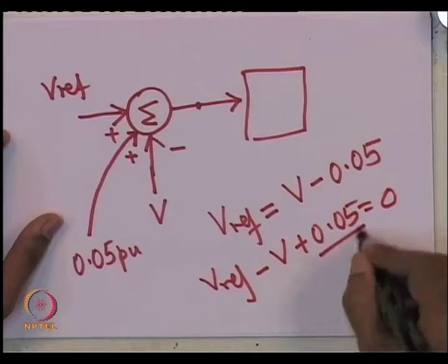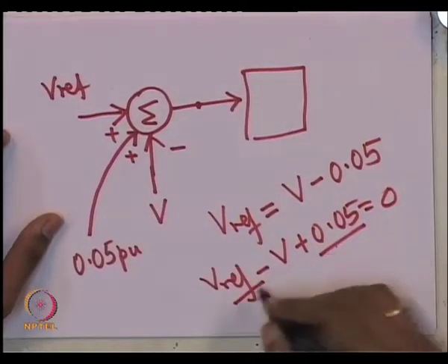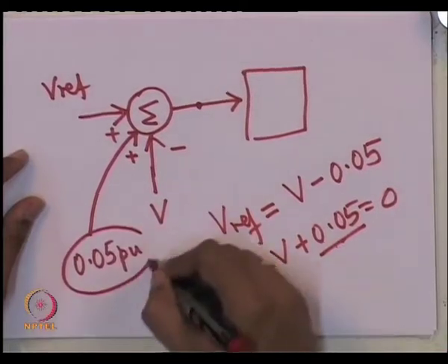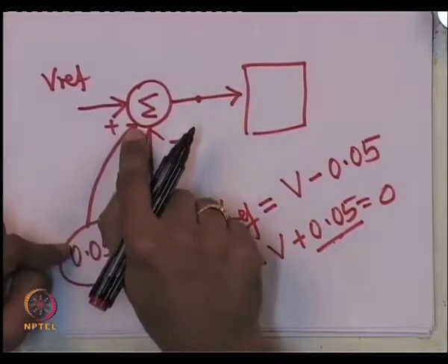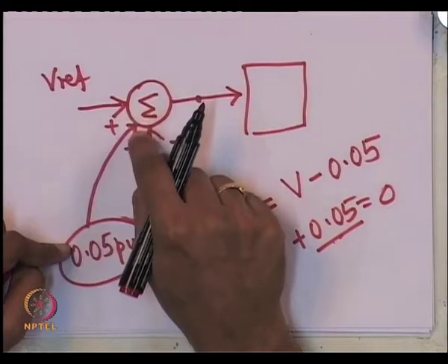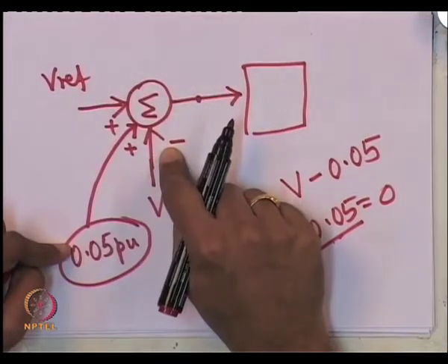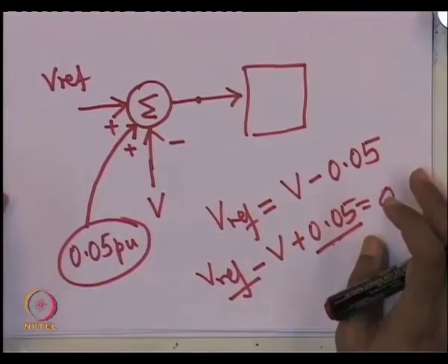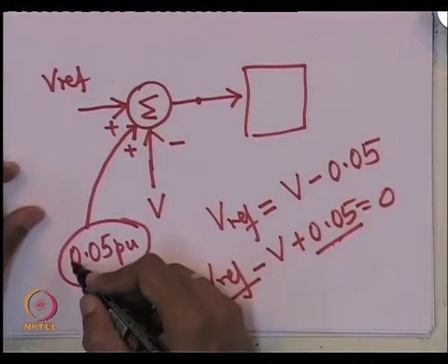So, what in effect by doing this I have done is increased Vref. Okay. So, if you have any additional signals adding on to Vref, they in effect compromise on this voltage regulation function. V will no longer be equal to Vref. Okay. So, for example, if there is an overfluxing situation, you may adjust,